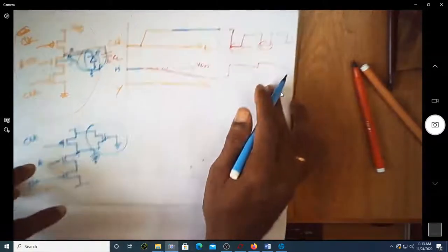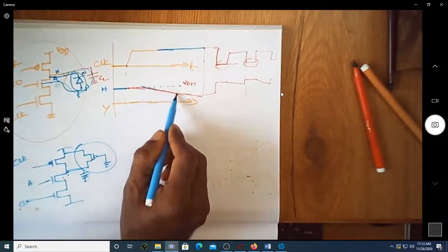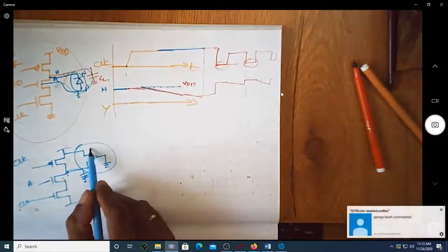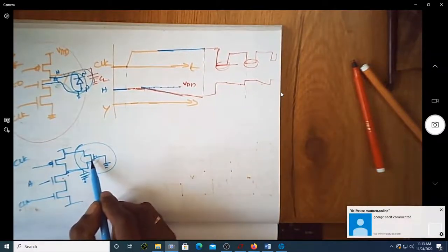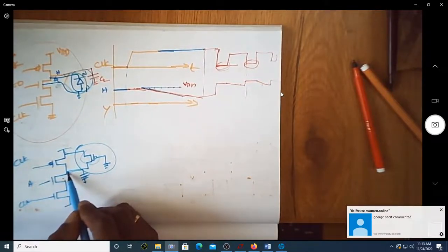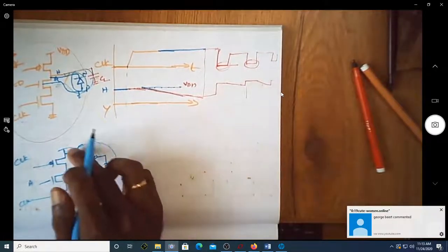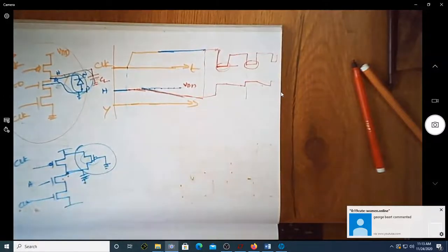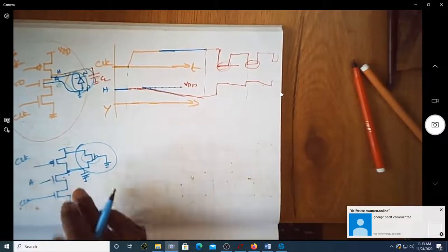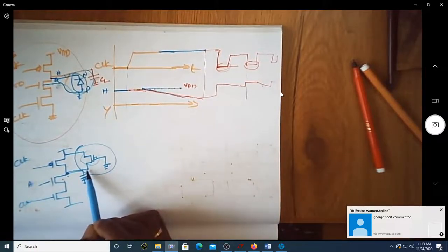So whenever this voltage tries to drop down here, this is again made equal to VDD because this is always on. Since you are grounding this, it will never let the voltage over here go down, because this is going to provide the required charge for this to be maintained at VDD. But you can see this will certainly have an issue.